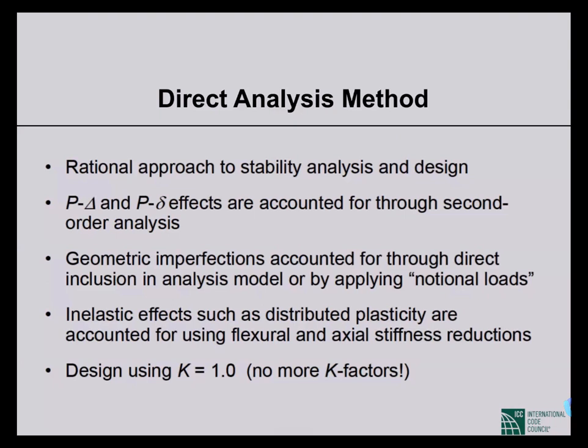So our usual practice is to go for effective length method, having K. We have to determine K. We have to understand what should be the value of K, which is effective length factor. So our buckling analysis depends entirely on what the effective length is. But in direct analysis method, the method was developed actually to avoid that problem.